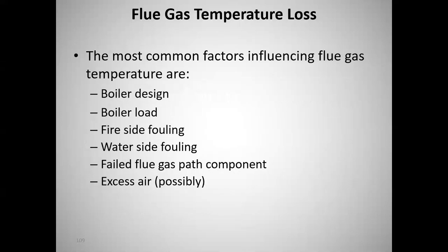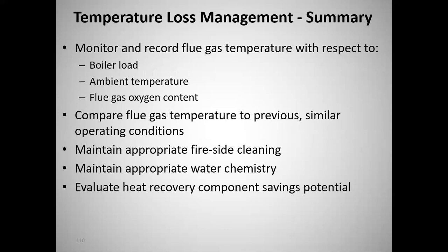Okay, the most common factors influencing flue gas temperature, and this just summarizes what we've been through. So I'm not going to read back through those for you again. Okay, so the temperature loss management summary. This is what we need to consider. Monitor and record flue gas temperature with respect to boiler load, ambient temperature, and flue gas oxygen content. Okay, we'll get into that.